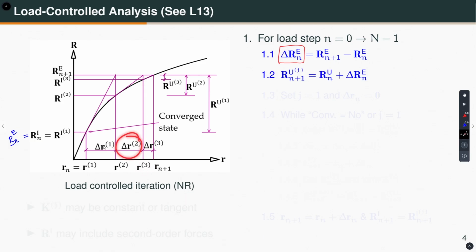This is the new incremental displacement. So, the previous we were here plus this. So, this is my current displacement, and at this stage I have some unbalance, which is reduced, right? And I do again another tangent here. So, I continue doing this until my unbalanced force vector satisfies a convergence criteria which we have discussed in this